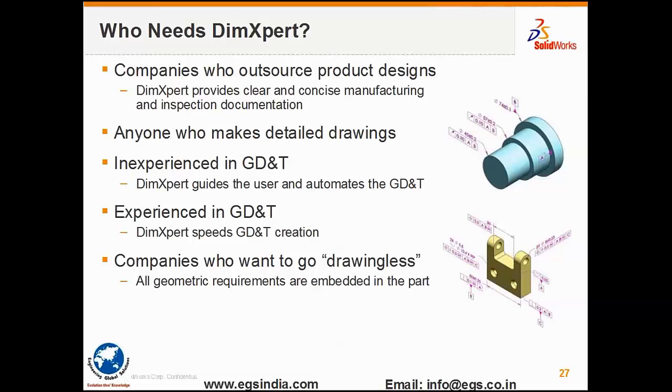So who needs DimXpert? Companies which outsource product designs, anyone who makes detail engineering drawings, those inexperienced in GD&T, and those experienced in GD&T who want to automate the process so that people downstream can look at it and replicate it. You can also solve customer related queries and high-end customer issues by going through your tolerance stack-up analysis using popular software such as Segment, which works inside SolidWorks. And companies which do not want to waste paper and want to go to a drawingless approach also use DimXpert.